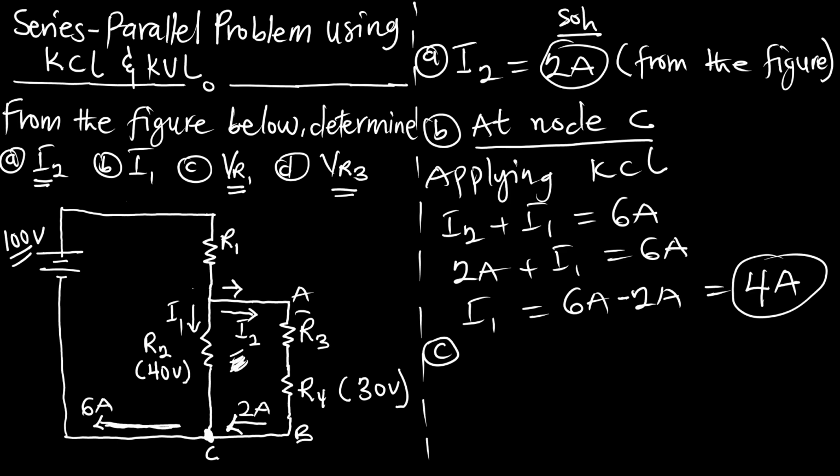Is that true? Let's call the voltage across resistor 1 V1, and everything across the final resistance here, let's say, V2. Okay, so we call it V2. They should sum up to the 100 volts, right? Now, if we have this resistance, the V2, we know that the voltage across R2 is 40 volts, and it is in parallel to all these parts, and we know that parallel circuits have the same voltage. Are we okay?